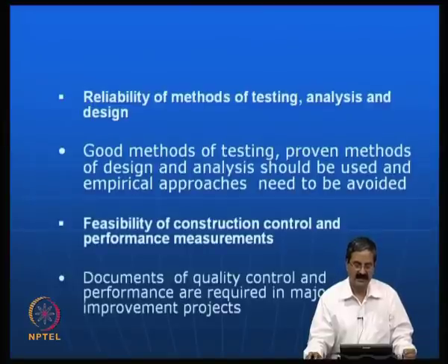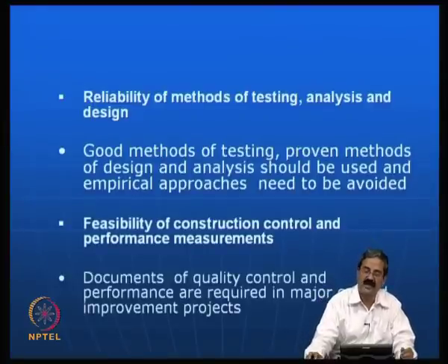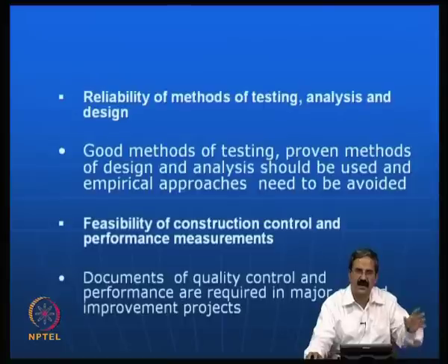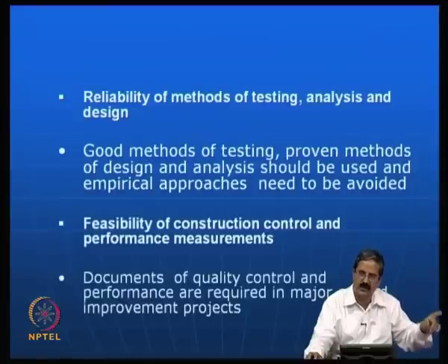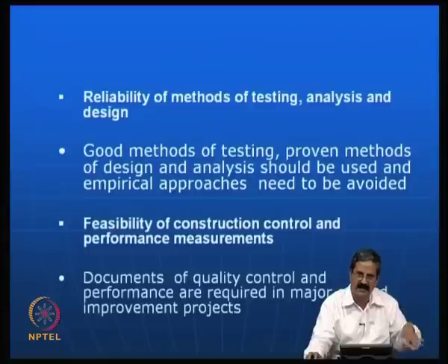Then proven methods of design and analysis. Actually what is happening in some places is that they do not design things properly. They say okay, the soil is the same as that soil. I have a sandy soil here, and in that project also they have a sandy soil. They used a particular ground improvement technique, so I want to use the same thing here, same spacing, same length. That is not correct. They will just justify that because the soil is the same, I can have the same design. So, that may not be correct.